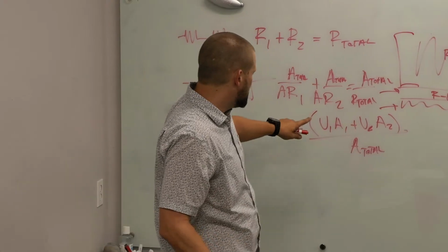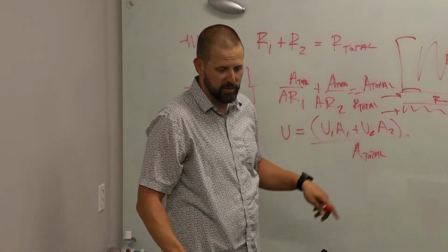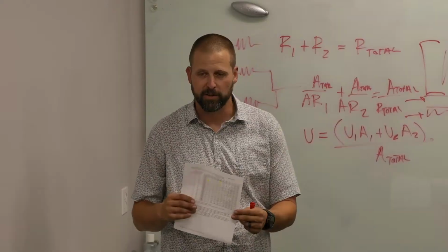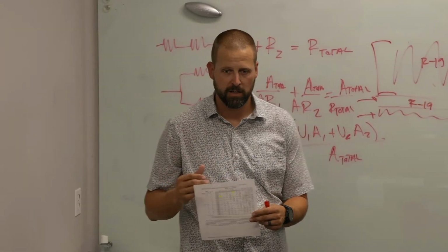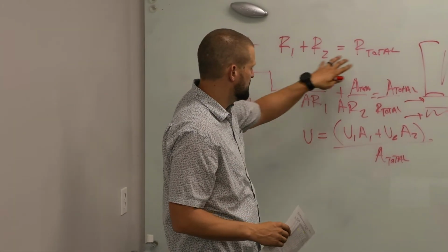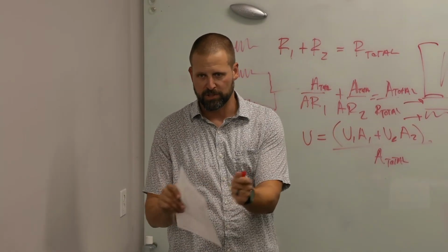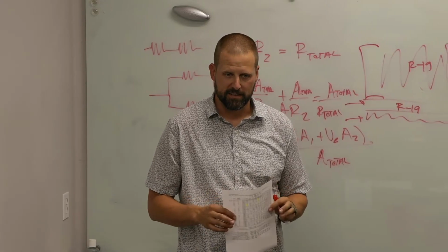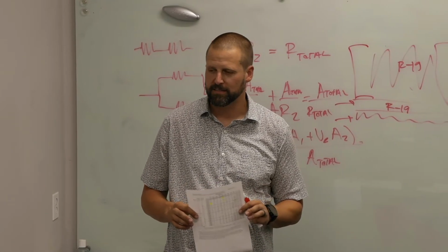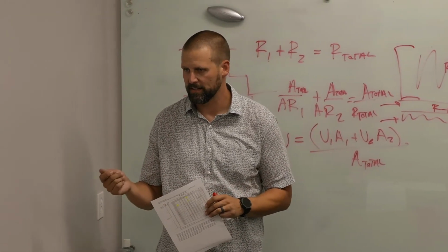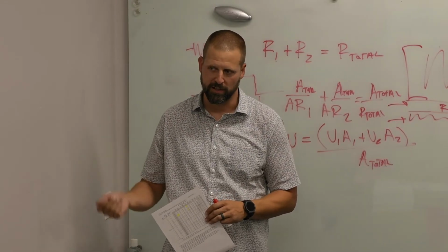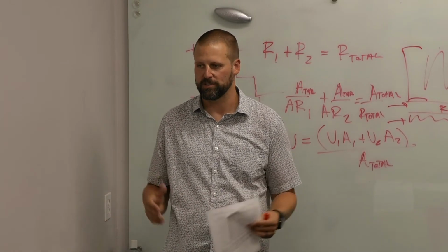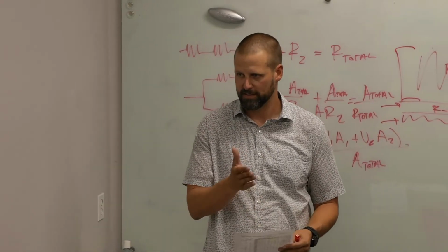We piece together assemblies. So if we have a metal framed wall in front of a concrete wall, we'll add them up in series. And it would kind of push these tables together. There are more advanced ways to calculate U values or U factors, more so on the windows side, that can sometimes give us credits. If it's a big enough project, we can go to a specific consultant to help with that.